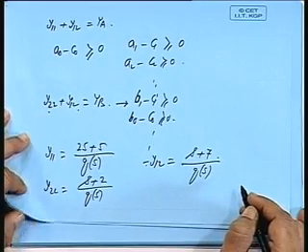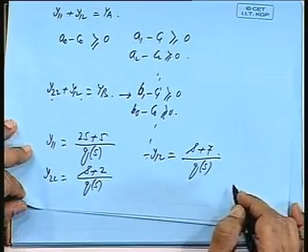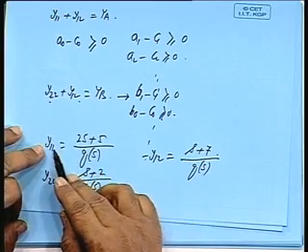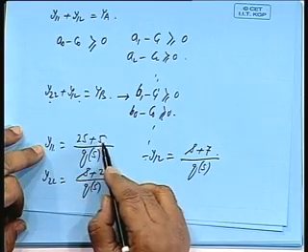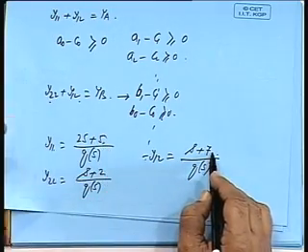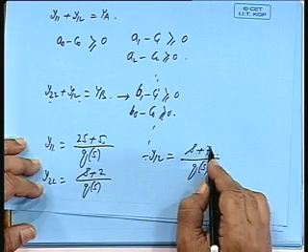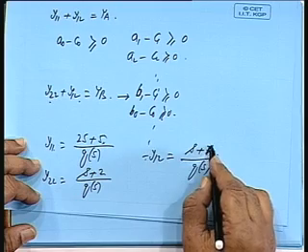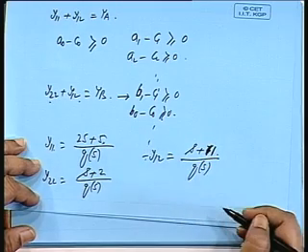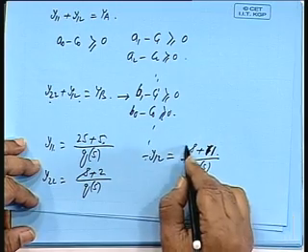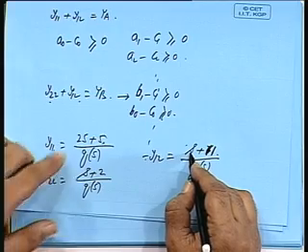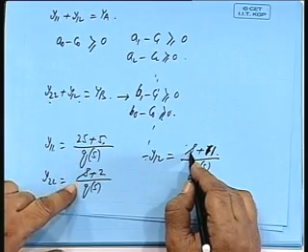Is it possible to realize this? No. Let us see y11 and y12, the coefficients. First coefficient 5 minus 7 is negative, so it is not possible. All right. So, this must be less than 2. If it is s plus 1, yes, it is possible. Suppose it is 2s plus 1, then this is all right, but this is not satisfied.